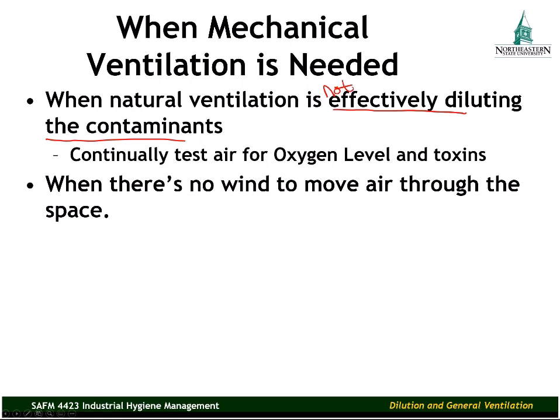Or maybe you're in a situation where there's no wind to move air through the space. Maybe your building is in an area where natural airflows are blocked by other buildings or trees or other structures. Or maybe the workspace is inside a tank, inside a pit or an excavation where you can't get that natural cross ventilation going. That would be a situation where you would need mechanical ventilation.